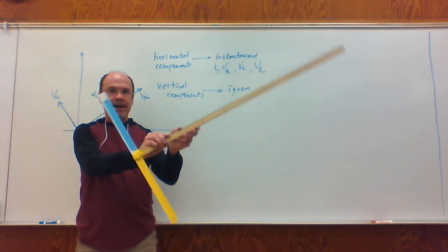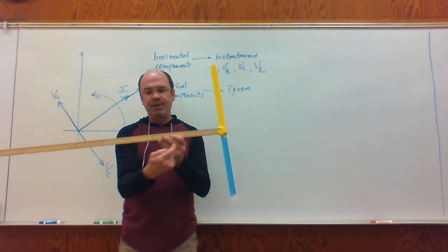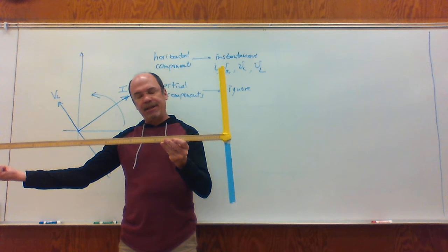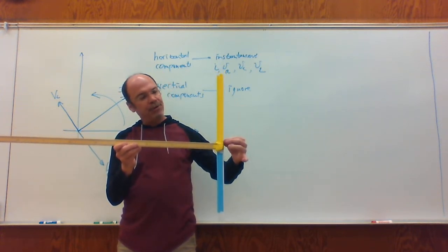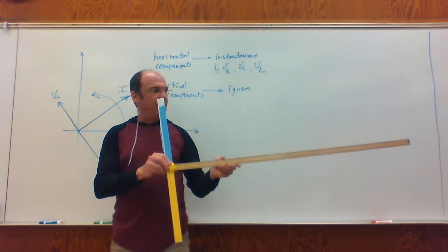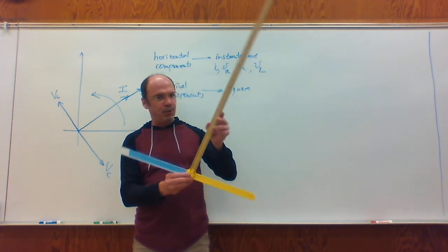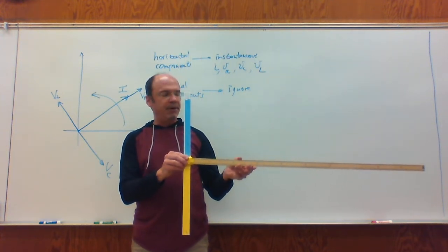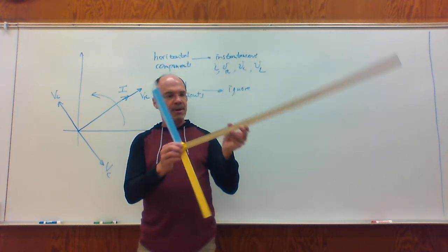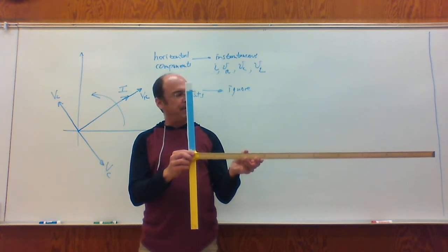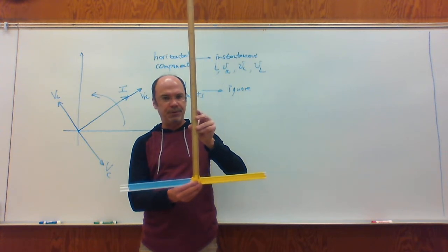If I rotate it around half of a cycle, I end up this way. My horizontal component of the current is a negative maximum. That should mean that the voltages across the inductor and capacitor are also zero. Okay, so as I rotate this, what happens? If I start in this orientation and rotate a quarter of the way around, the current starts at a positive maximum, gets smaller and smaller, and approaches zero. The voltage across the resistor does the same thing. It starts at a positive maximum and approaches zero.